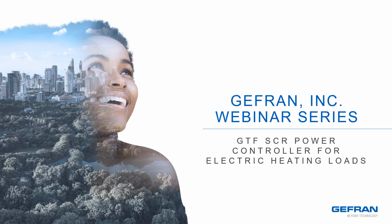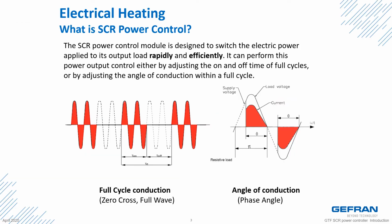So let's get started. So what is an SCR Power Controller? An SCR Power Controller is an electronic semiconductor device designed to switch power at its output connection rapidly and efficiently. There are two primary methods of adjusting power. Full cycle conduction, where we adjust full cycles over a time period, or angle of conduction, where we adjust the angle of conduction within a full cycle.